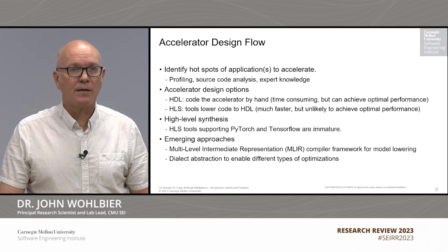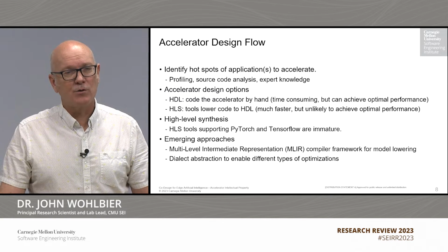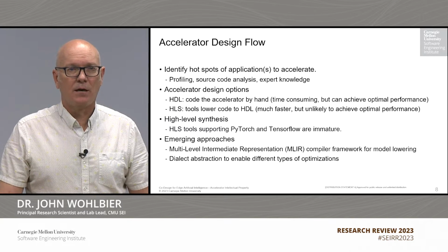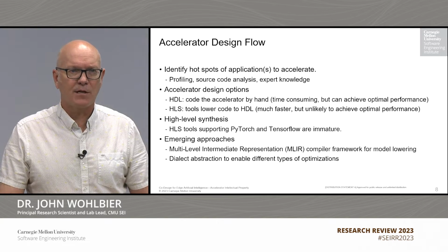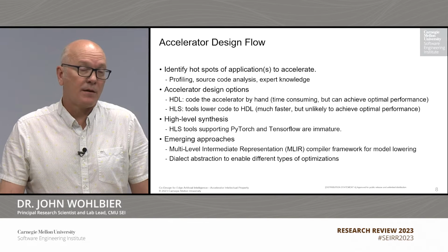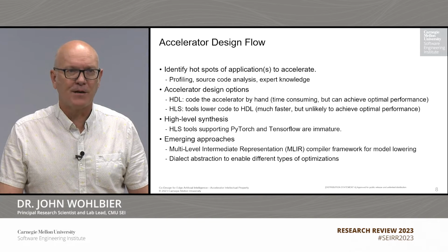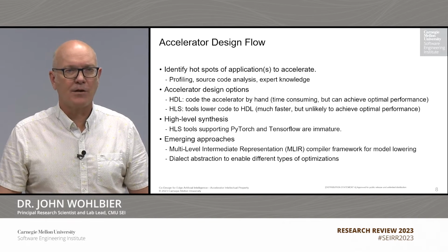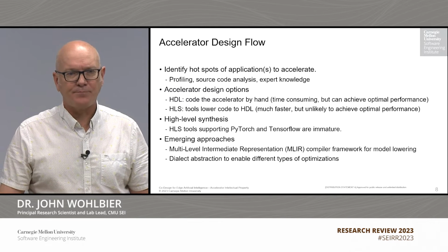Possibilities for hotspot identification include traditional profiling, but then also annotated source code analysis. And there are lots of techniques around that to identify accelerators. And then there's never a substitute for expert knowledge when deciding how to take your overall application and turn it into a system on chip.